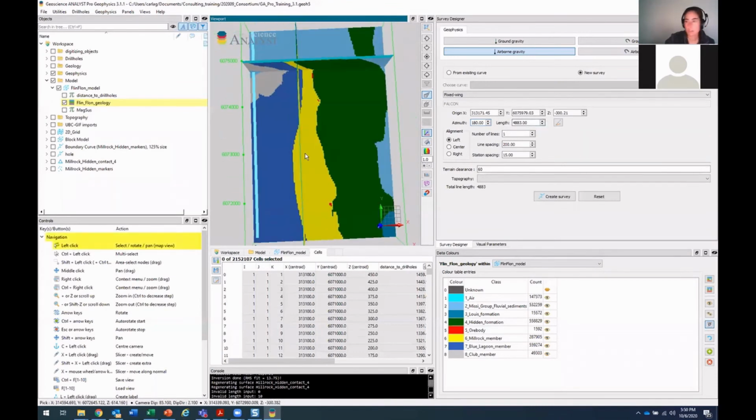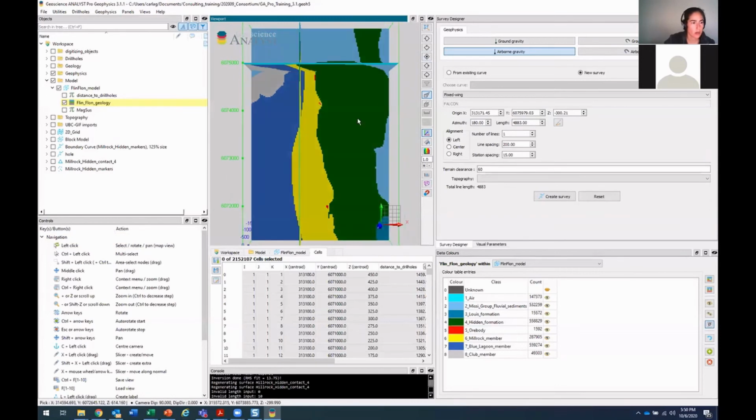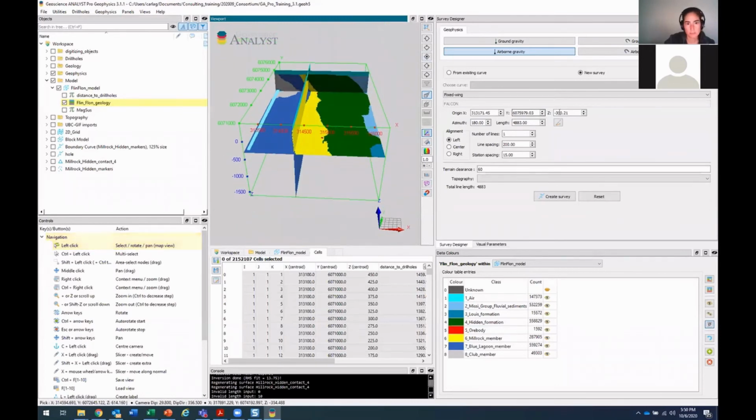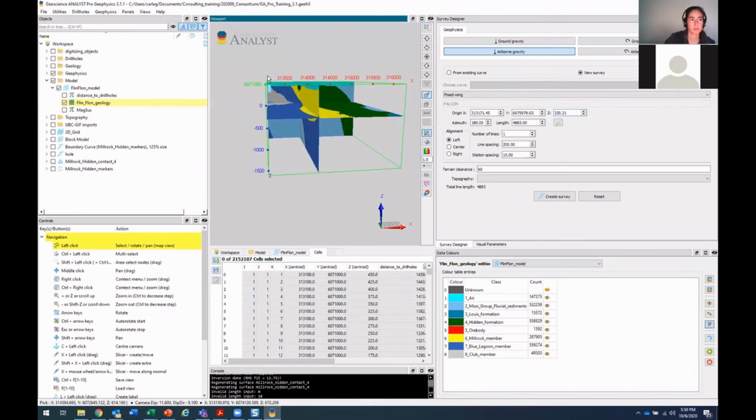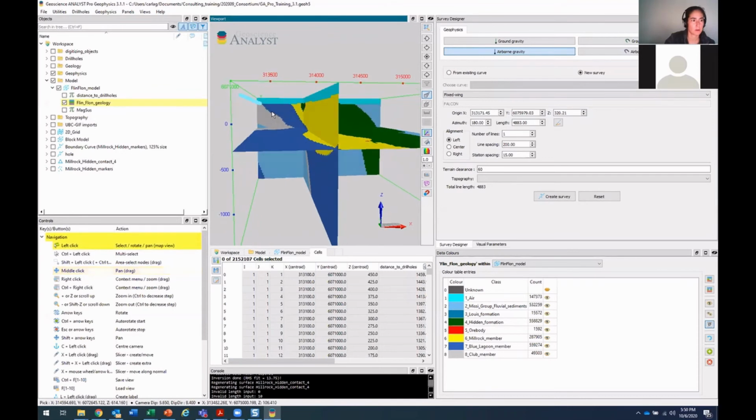And the length of it looks pretty good to me. One thing you can do here is bring that Z origin up. Right now it's where my section was, so at -300. You can change that up to 320. And that's approximately where the topography is on that model.